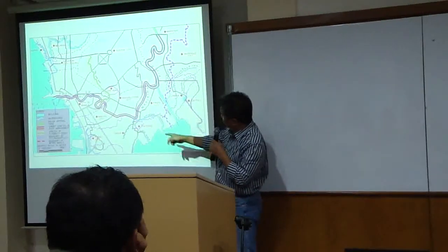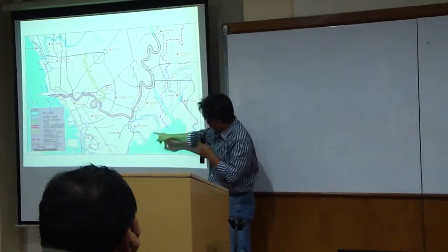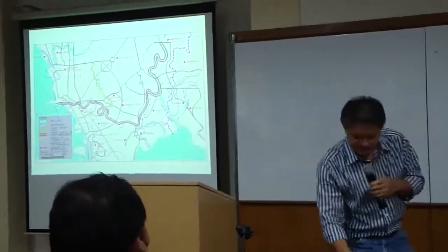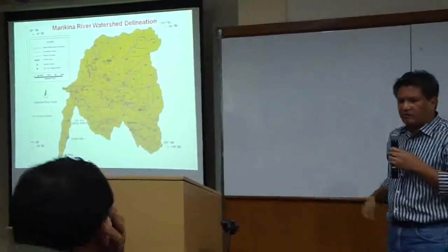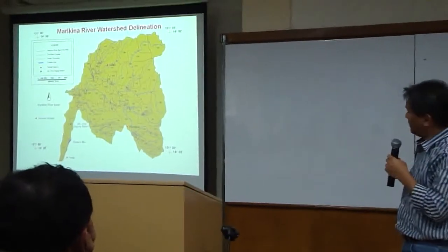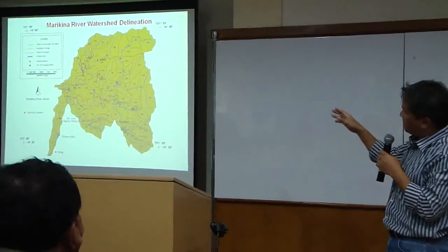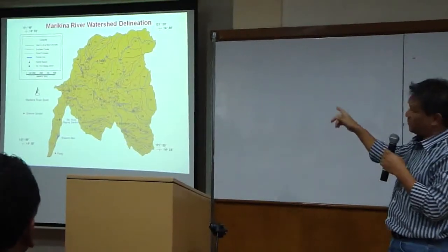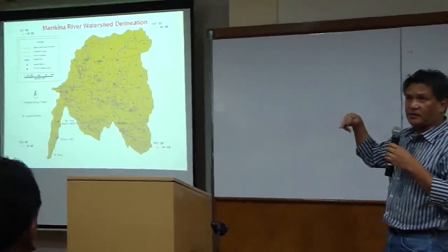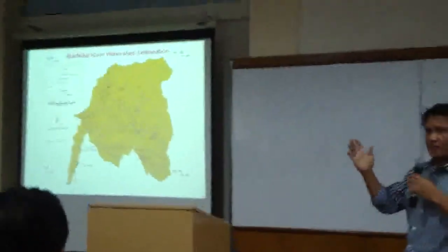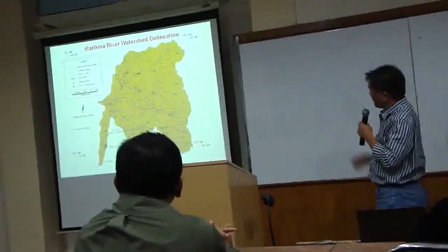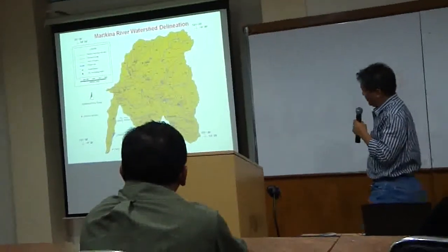So there are three bodies of water, Manila Bay, Laguna Lake, and this point, and then this point where it becomes a boundary condition of the model. The Marikina watershed is modeled using a watershed model, and the watershed geometry or delineation is given to this. It's about 168 subbasins, times 2 left and right overland flow planes. It's quite a considerable discretization of the watershed.